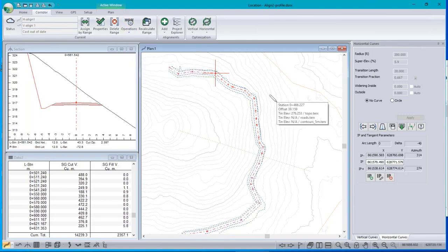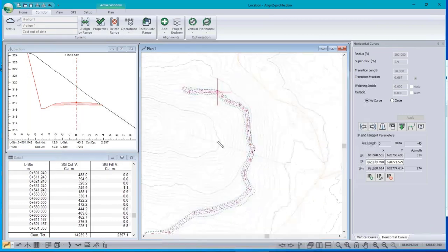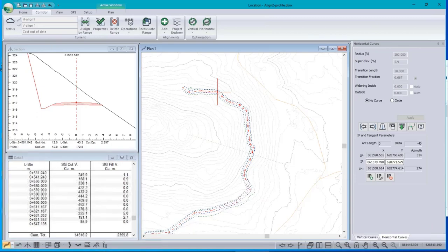Now, let's look at this with curves. So I'm going to put in a curve here. It's a different problem. So essentially, we've solved the problem here. We've found a solution where the total cut is 14,000, and I don't think that can be reduced. You know, I can easily increase it by moving a point up the hill. It's going to cut more, but I don't think we can reduce it. We've got the minimum cut here.